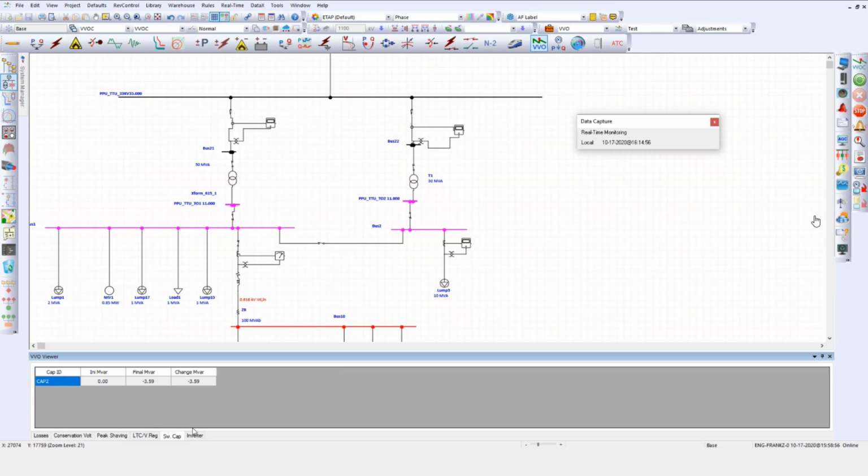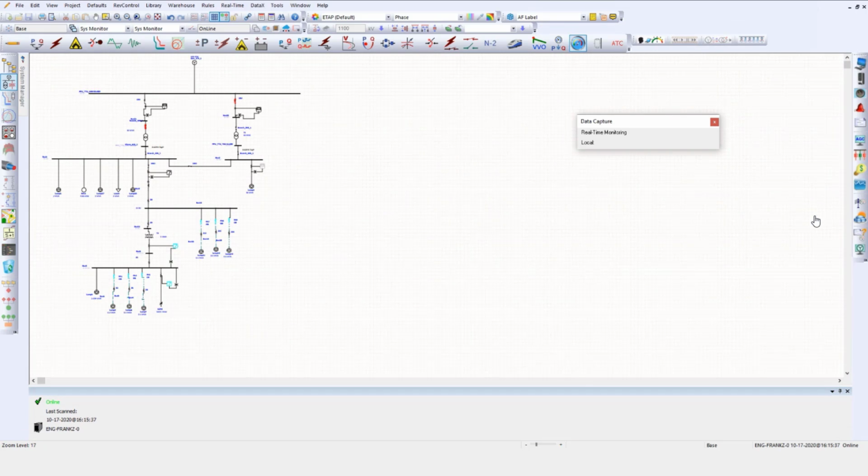And you can define the speed or the schedule at which the VVO runs, which can be on a preset interval, or on demand, or event driven, or any other combination that you may choose, such that you can get continuous volt-var optimization on the feeder circuits. There are many different approaches for doing so. You can run volt-var optimization for the whole day and then not run it the following day, so you can observe the differences between having volt-var or not having volt-var in the system. Or you can do it on a periodic basis, which is good in terms of comparison.